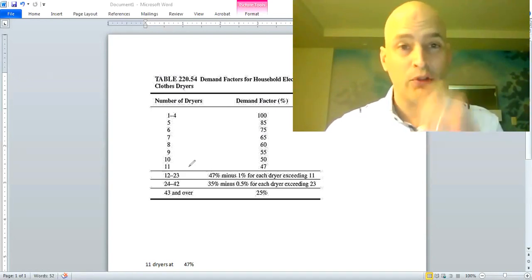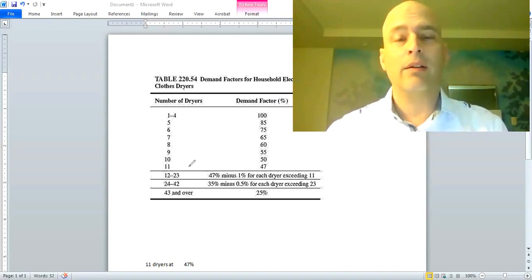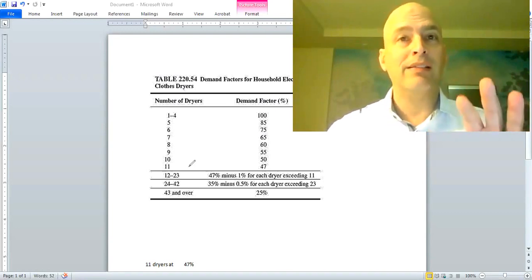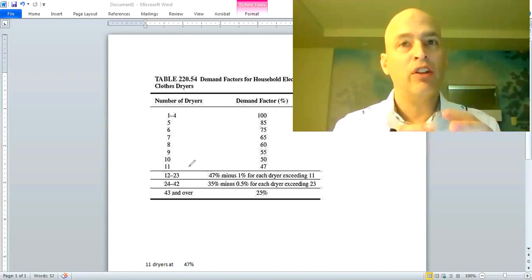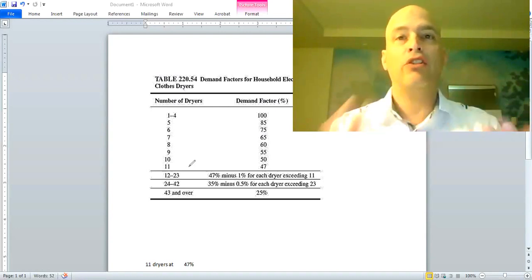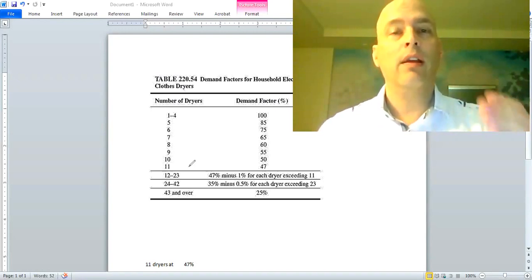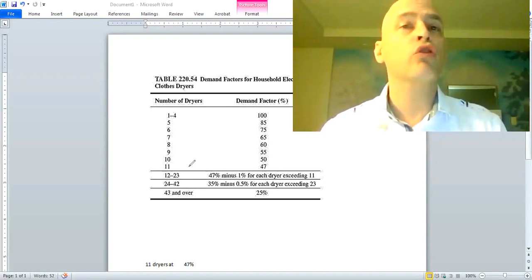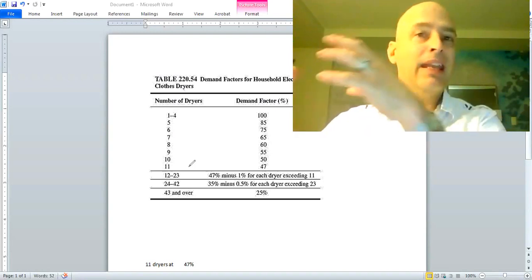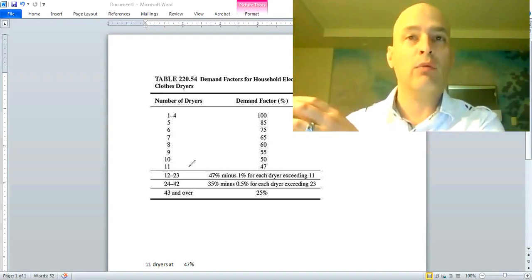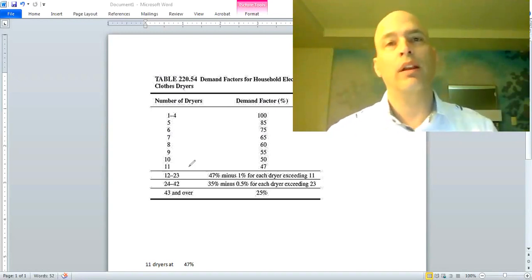And correct me if I'm wrong, I'm sure some of you have probably done a load calculation for a residential dwelling. Keep in mind, this table is not a branch circuit calculation. It is a feeder calculation. So what we're doing with these numbers, we're not trying to divide this number by 240 volts and determine the ampacity to run a couple of branch circuits, Romex and breakers on it. What we're trying to do is figure out, just on the feeders on the surface of the building, what this part of the load represents, so that we can add it along with all of the other calculations we would have to make for the service for that dwelling occupancy type.